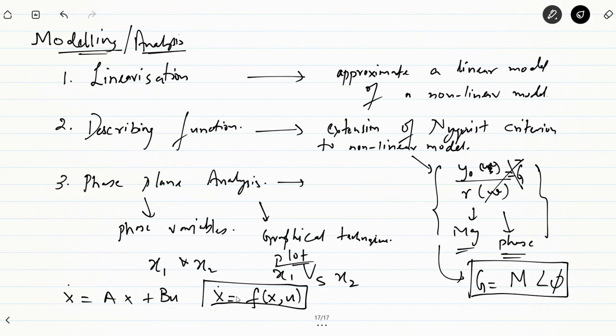So from that we can then obtain the state variables, and obtain the plot of one phase variable versus another phase variable. Those trajectories, those portraits will determine whether our system is stable or not. What will be the limit cycles, chaos, etc. Bifurcation, saddle points, many things we will all be understanding from the phase portraits of these systems now.